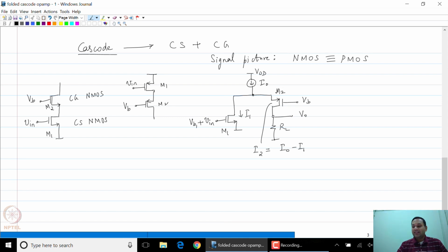As you can see, the NMOS is biased as the difference between the current source I0 and the bias current of M1. And needless to say, you should apply an appropriate VB and of course VB1 at the gate of the PMOS transistor M2.